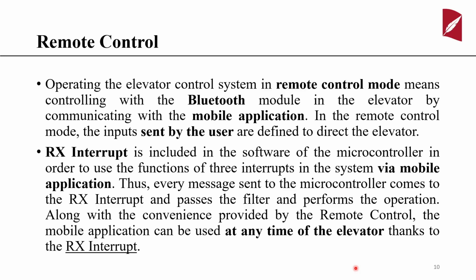Thus, every message sent to the microcontroller comes to the RX interrupt and passes the filter and performs the operation. Along with the convenience provided by the remote control, the mobile application can be used at any time of the elevator, thanks to the RX interrupt. This is the important interrupt in my project.